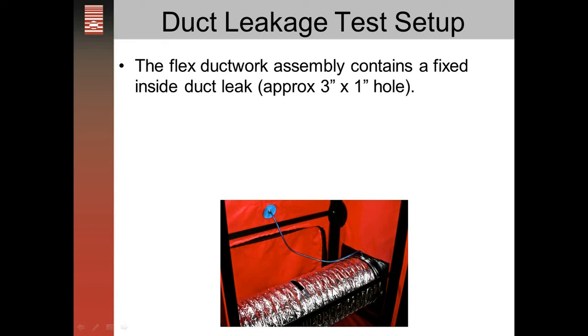So during a total duct leakage test, you'll get air leakage through this space, and also leakage from where the square transition's Velcro connects to the plate. During the duct leakage to outside test, you'll have the blower door running, keeping this space at the same pressure as the ductwork. And because there's no pressure across any of these openings, there'll be no duct leakage.